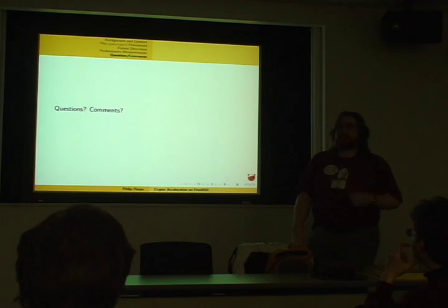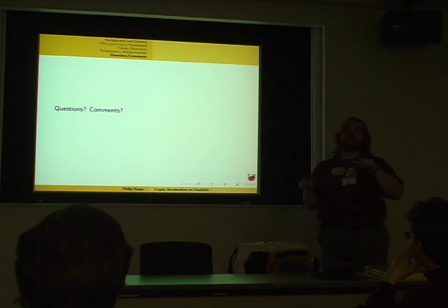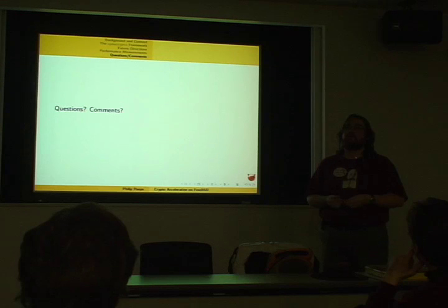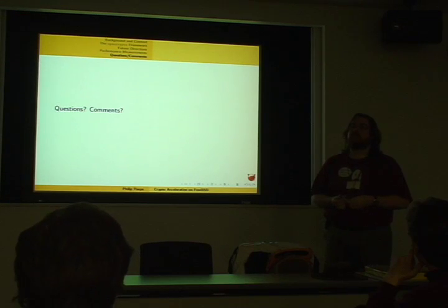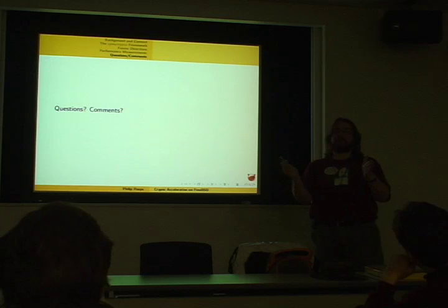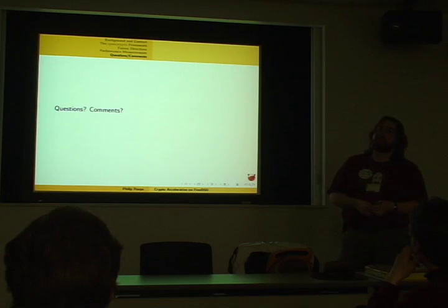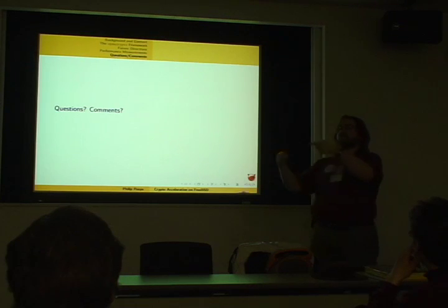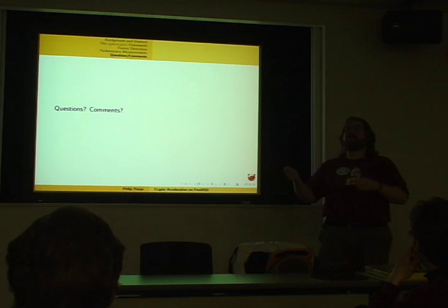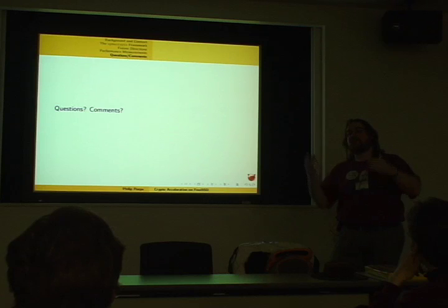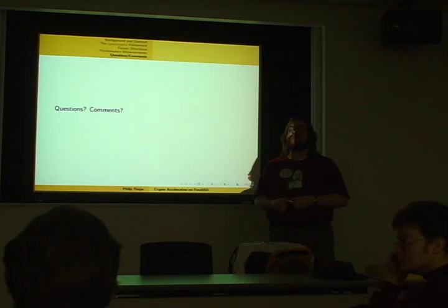I think, if I understand the question correctly, you have problems with packets not being ordered. Yes, that's going to be a problem, because the crypto engine will want to do the operations in order. You will need to serialize them, so that's not going to be good. If we introduce more parallelism in the layer, then you could do your operations out of order. You could send one packet to one crypto accelerator, have it done, wait for it to complete, send another packet down to another one, wait for it to complete, and then when they are all done, you just pass them on to wherever they're needed.